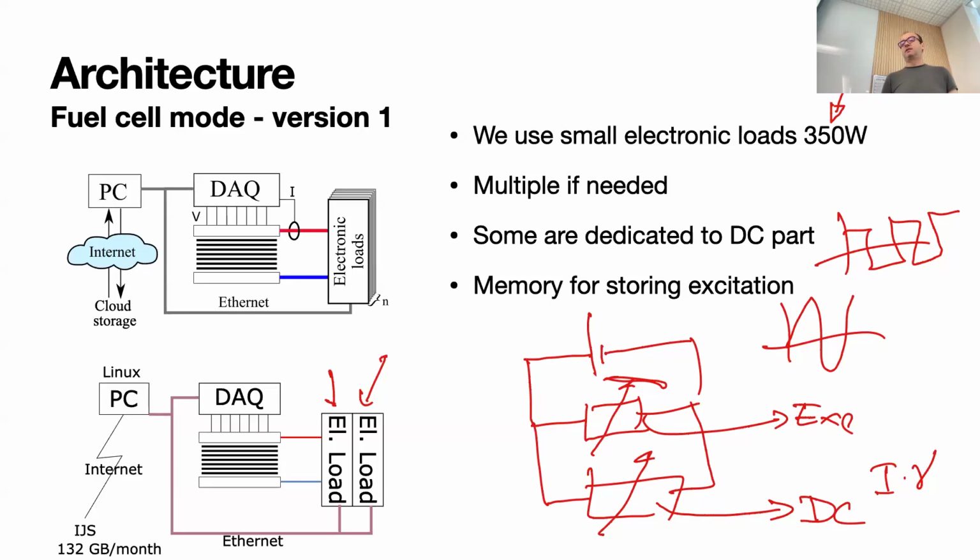You have to be quite careful when buying this stuff. What is the frequency bandwidth of the electronic load? Some of them are really low, below 300 Hertz. You can easily find electronic loads that go sufficiently high for a price tag around $1,000 US, which means that you can do this quite cheaply, and you are building a modular storage.